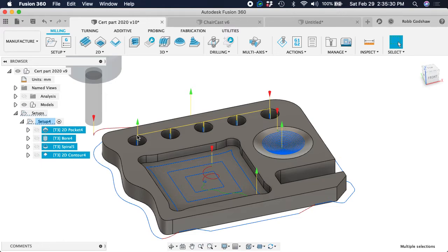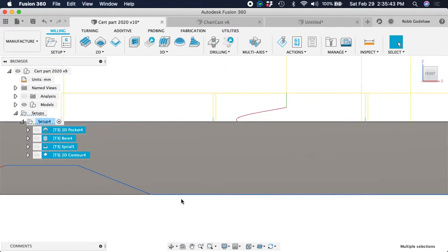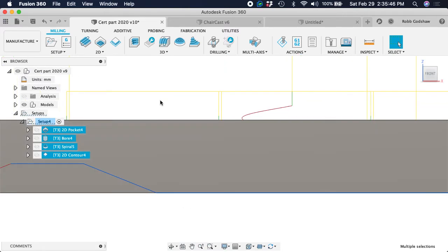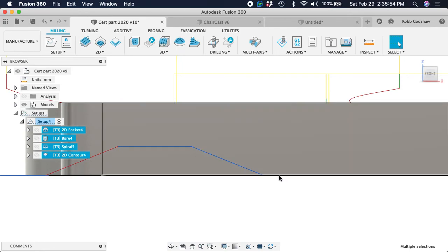That would be amazing. Oh, I'm sorry, I forgot something about the contour. Go into contour. This actually isn't going to cut all the way through. So if I measure the material, and it's exactly 1/2 inch, it's a miracle of manufacturing. And I set the machine to cut to the bottom of the material, it's probably not going to cut all the way through because the machine could deflect. Both the head of the machine can deflect upwards and the bed of the machine can deflect downward.